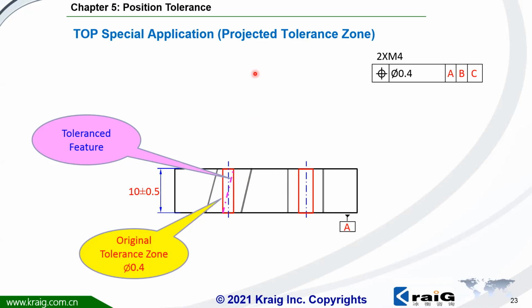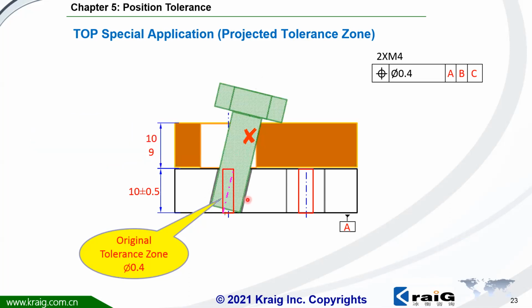And next, you're going to put a threaded bolt, or threaded screw, inside. What if this hole is tilted, but the axis is still within the tolerance? You see here, the threaded hole is tilted, but the axis is still within the tolerance zone. Next, the bolt will be extended, because you control the position of this portion, but the bolt is from here to here.